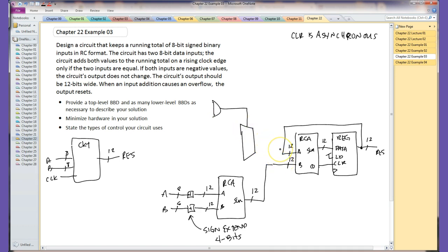What we messed up here is that the output of this gate is controlling this mux. The mux is either adding the output of the sum or it's adding 0. That was what we agreed on when we first started this problem. Initially we haven't done anything on this mux yet. We haven't put the numbers in, and we don't have to worry about that. We'll worry about that in a minute.